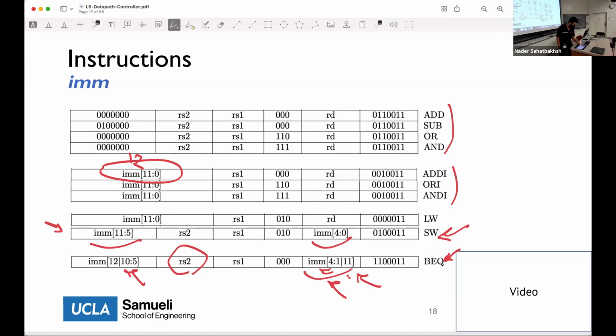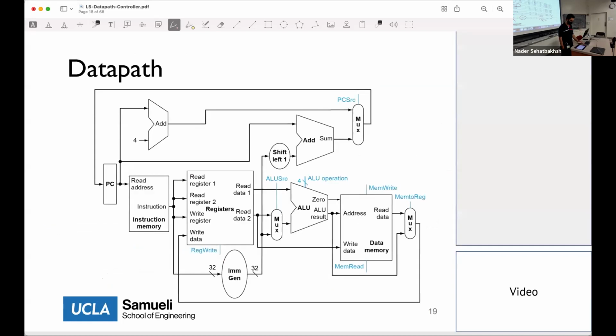Another thing is that they wanted to keep the 12th bit, the most significant bit, on the top in order to show where the address is jumping and so on. So it's more about the way the decoding of the branch predictor works, which we're going to talk about later. And no matter how you structure this, some of the instructions will look weird. Any other questions? As I said, in terms of the actual decoding part, as long as you know where each bit is, the rest of it is just wiring, so it doesn't make any significant difference.